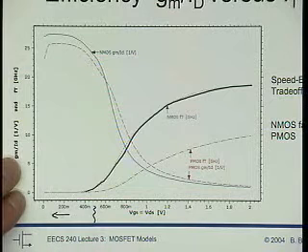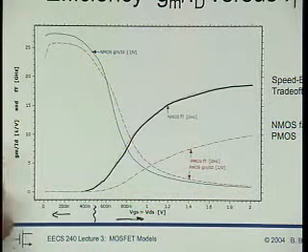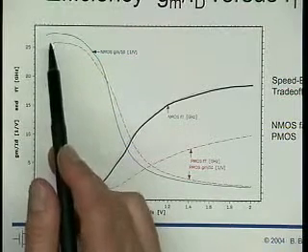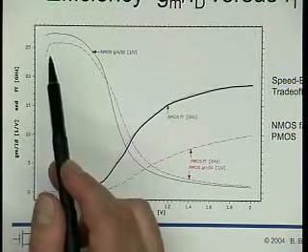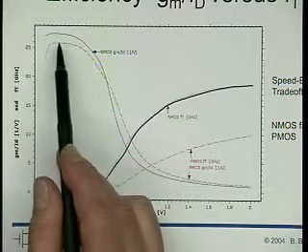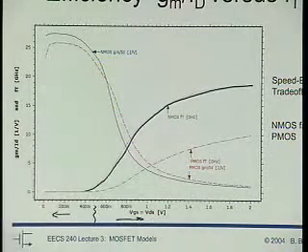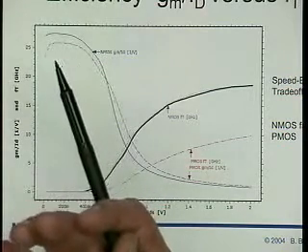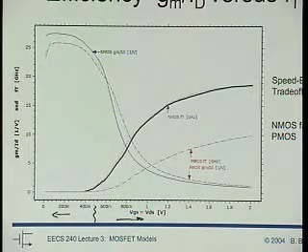So down here we are in weak inversion, and up here we are in strong inversion. Also shown in the same slide is the efficiency, GM over ID, plotted for N-channel and P-channel transistors, and it says that, as we've seen, we really would like to use small VGS.